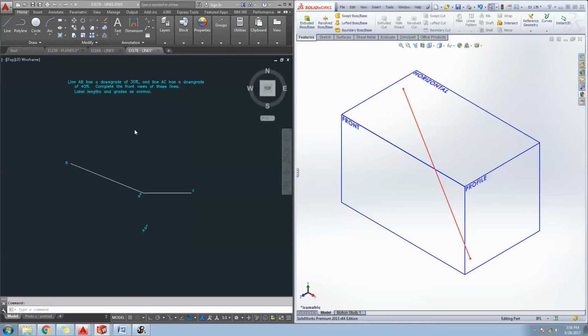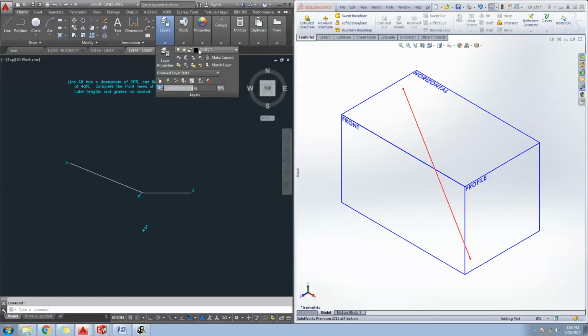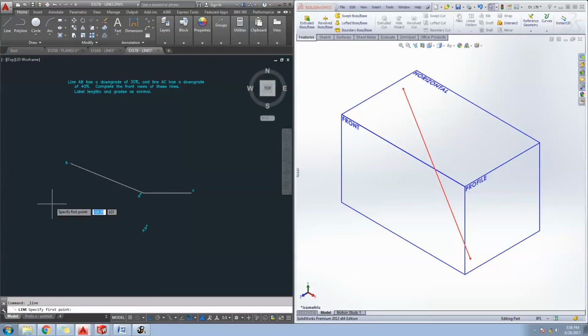So, starting up. First thing we're going to do is make a folding line, and we'll place it right in between the horizontal and frontal views. I can tell that this is the horizontal view because of a little subscript H right there. And I know this one's definitely a frontal view because it included that F right there, that superscript F. Alright.